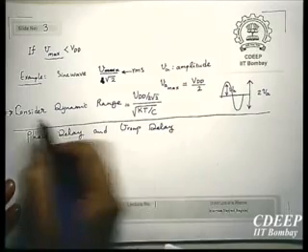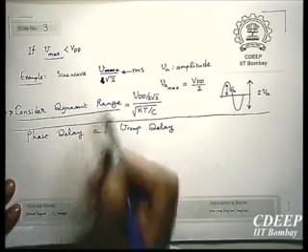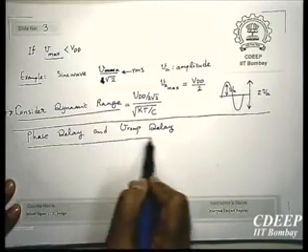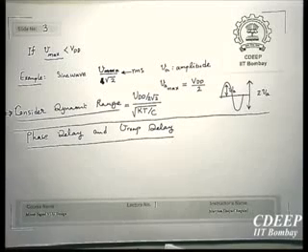First we explained the concept of dynamic range, and now we talk about these two, because usually these concepts are not covered properly. I want to give you an introduction because when you design a filter, you need to be careful about these two, specifically the second one. If I deal with a large value of voltage, I'm not so concerned about noise, at least for passive circuits, but group delay is something you should always be careful about.